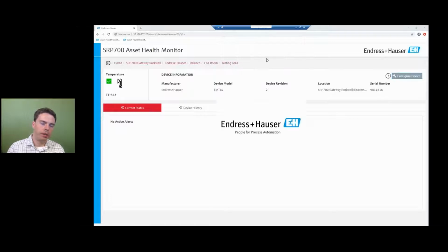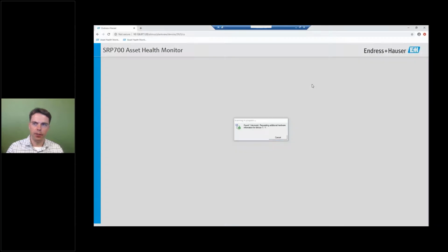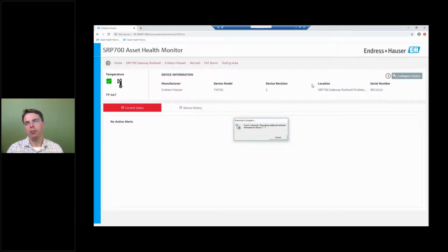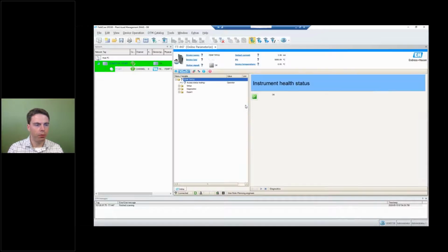So then in the background, as we explained, FieldCare needs to be installed on the client with all the drivers here. So we use FDT/DTM technology, but we also have over 3,000 devices with DD files here. So we can also interpret DD files. So we can use both technologies in case you're a bit familiar with that. So it will automatically look for the device. It will connect. As we have HART signals here, and HART is not incredibly fast at 1.2 kilobit,